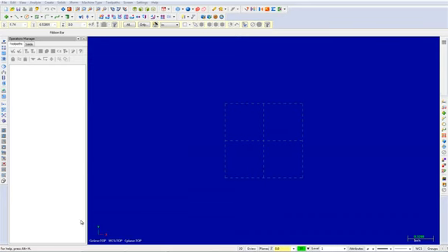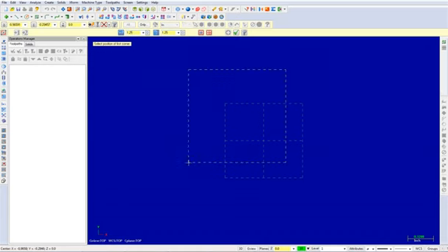Select the Create Rectangle command. Enter both a width and height of 1.25 as shown. Once complete, press Enter after typing the values to see a preview of the rectangle. Select the origin. Once complete, you can select the OK button to exit the rectangle command.